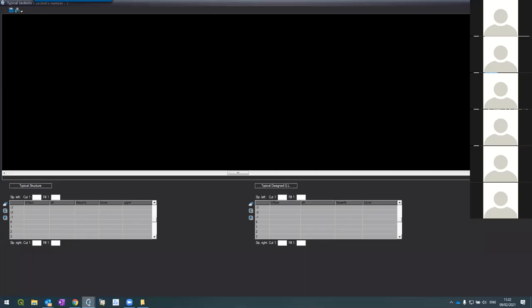On road 2, the system divides the road into 3 segments. The first one is from 0 to 27 meters, which is the beginning of the median. The median starts at 27 and ends at 208, and from 208 to 229 is the last segment. I will start, it's my decision, with the one with the median. So I'm clicking on the second segment and starting to define its template.